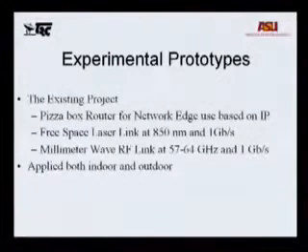So we're doing the prototype over several platforms. We started with OPNET to test out the concepts. And then we are right now doing a POX sort of router. Effectively, it's an edge router. It's all based on IP. We are doing both the free space laser link at 850 nanometer, running at about 1 gigabit per second, testing a link to see how much power is required, and so on. We are also looking at a millimeter wave radio link at frequencies of 57 to 64 gigahertz and at 1 gigabit per second. It's applied both indoor and outdoor.